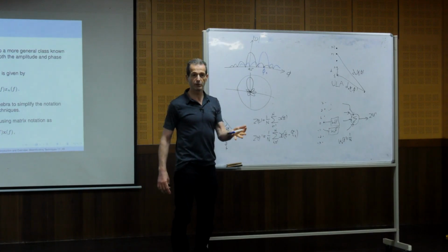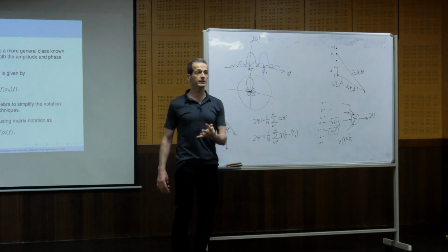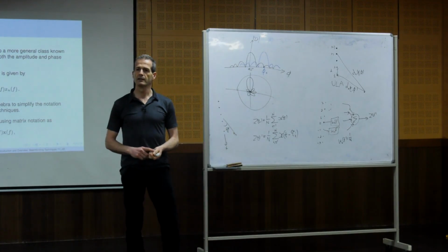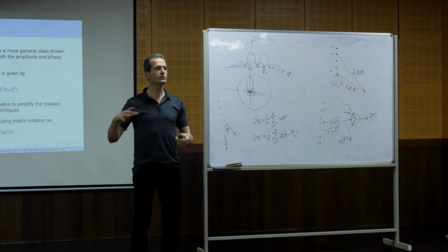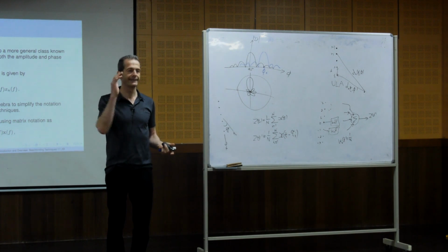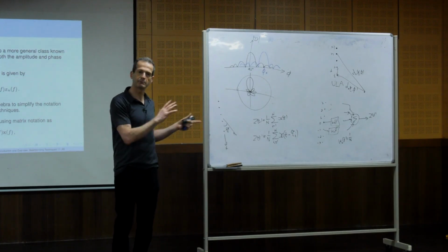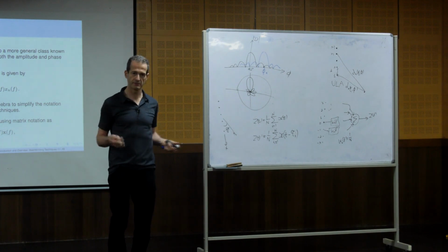We call this kind of beamformer a maximum directivity beamformer. Okay? So we will learn about it. This is a very common way, because maximum directivity beamformers are very important. Why? Because sometimes suppose that I design the weights in advance. It's not adaptive. I would like to design the beamformer in advance without knowing what the noise environment is.